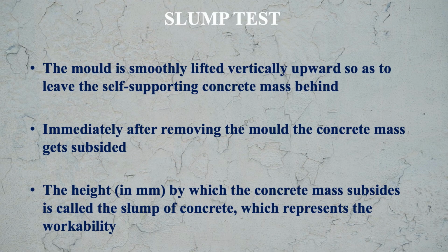Subsidence of the concrete mass will occur, so there will be a reduction in the height of this concrete mass. This reduction in the height is basically the slump. The height in mm by which the concrete mass subsides is called the slump of concrete, which represents the workability. And that way we associate this slump with the workability of the concrete.